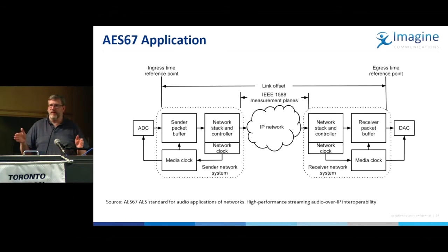And then it doesn't matter what source they're coming from, because all the transmitters are locked to the same source of PTP time, the 2059 time. So because all the transmitters are locked together, the receiver can ensure that it doesn't matter what the network delay is. One path could have been 1 millisecond, another path was 5 milliseconds, another path was 8 milliseconds. It's going to be able to reassemble everything together, so there's no audio-to-audio delay. So that's one application we have for our 2059 stuff.